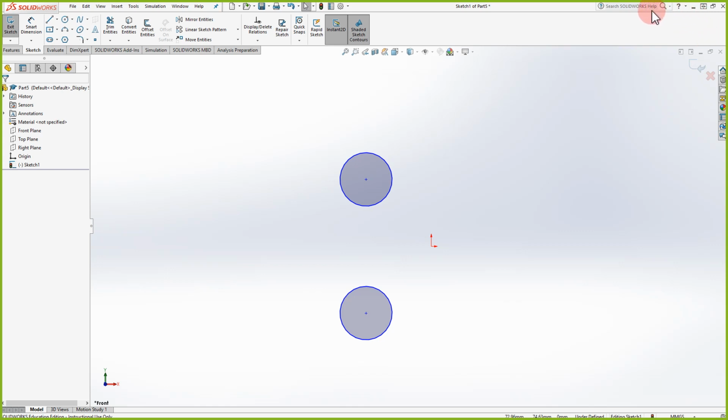What I do, and I recommend you do the same, is instead of using the help at the moment, just switch it to commands. Why am I doing that? Because now whatever command you are looking for, if you're in a rush, you can search it and it's going to find it. If I type in mirror, like so, now it's showing me mirror and dynamic mirror, which we're going to show you in a few moments, and also mirror.